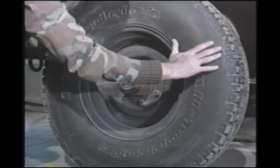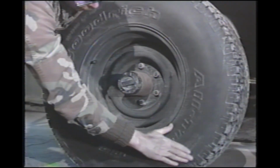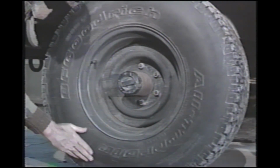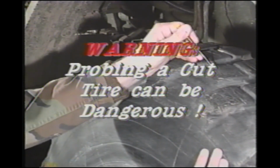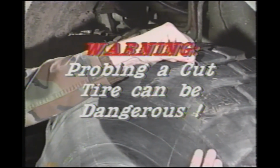Next, carefully inspect the sidewall for damage. If there is weather cracking, cuts, tears, or punctures, carefully probe with a blunt instrument to ensure the damage has not penetrated into the cord. Warning: probing a cut tire can be dangerous. A sharp instrument could cause an immediate tire failure or explosion. Wear safety goggles and do not probe too deeply.